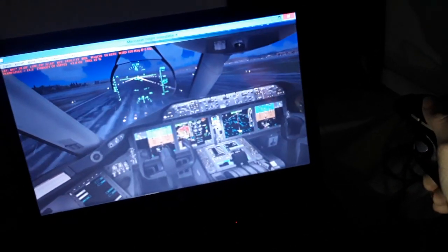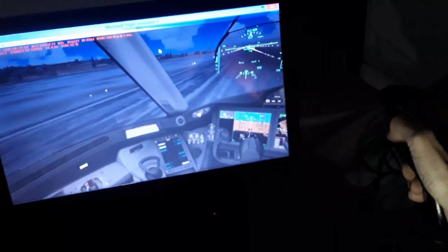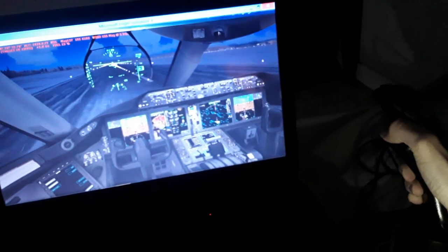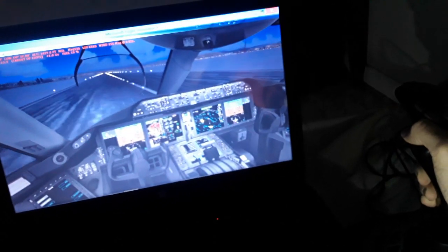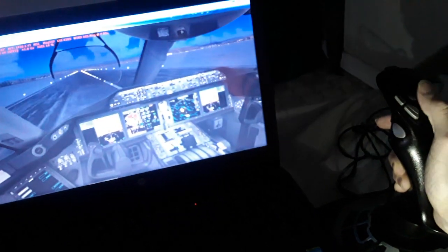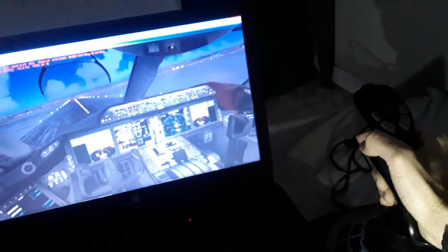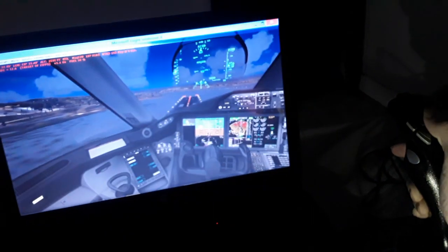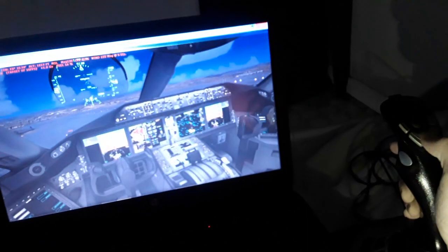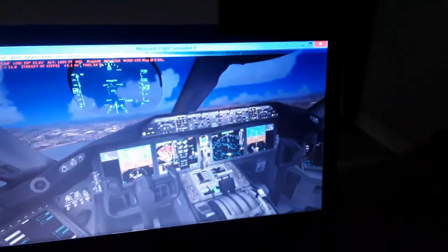So hold the yoke a little bit down, just like in the Airbus, until 100 knots. So we have 100 knots, 120, V1, we rotate slightly, like 9 degrees. So we have the takeoff, positive rate of climb, pitch attitude a little bit higher. So landing gear up.